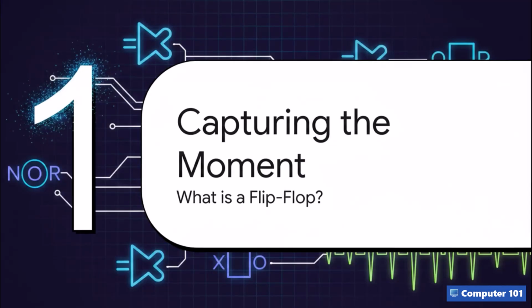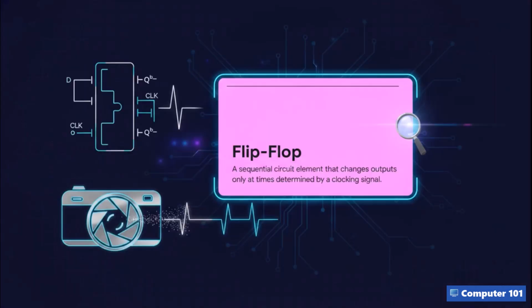Section 1. Capturing the moment. Before we get into the circuit diagrams, let's just ground ourselves in what we're actually looking at. At its core, we're talking about a flip-flop. Now, you know this is a sequential circuit element, right? It samples its data input, which we simply call D, and it changes its outputs only at very specific times, dictated by a clocking signal, or CLK.